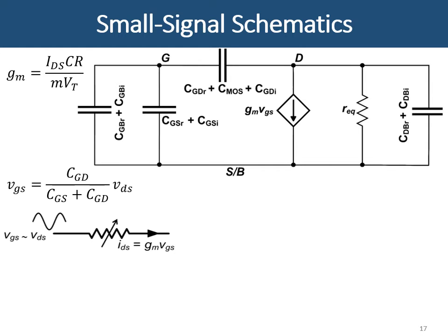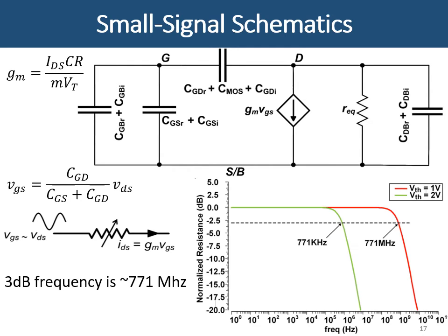At higher frequencies, the Y-flash operation is dominated by the capacitors, transitioning it to behave as an amplifier with capacitive and resistive contribution, rather than a pure resistor, which leads to a pole that degrades the gain function by 3 dB. Spectral analysis, as illustrated in the last figure, gives a maximum operating frequency range spanning 3 orders of magnitude corresponding to the state variable dynamic range.